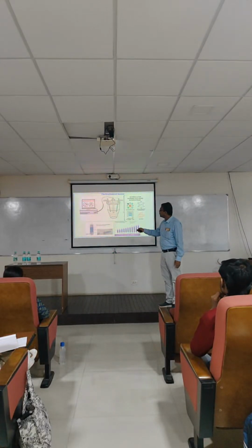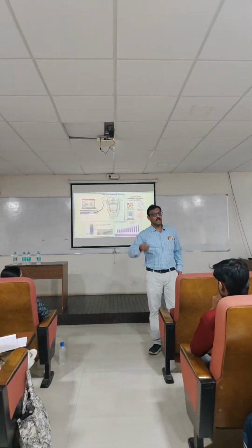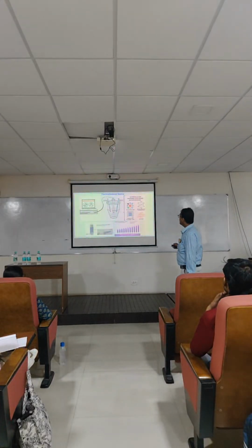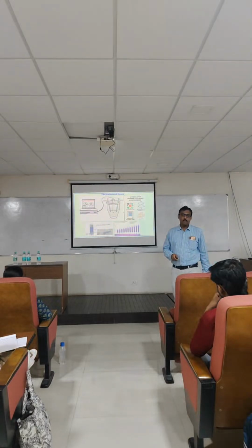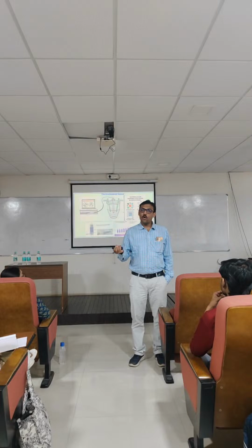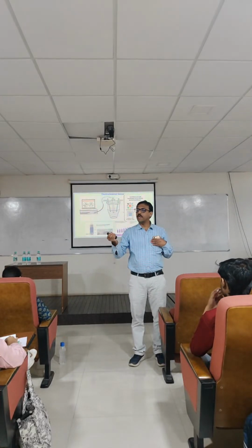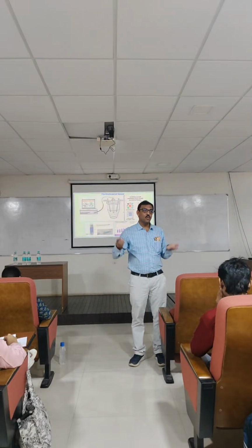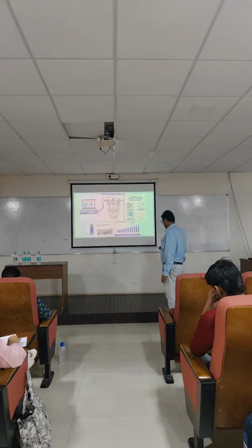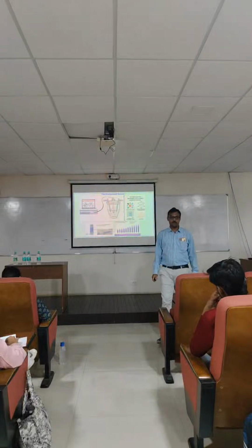Then we measure, this is called cyclic voltammetry, and from cyclic voltammetry, amperometry and other things we are also getting. So these are some signals we are getting from the electrochemical sensor. But this electrochemical sensor, whatever we do in the lab, you cannot always take it into the field. So in the field you will have to take some other system which is equivalent to that three electrode system which is shown here. So that's why nowadays you are getting this kind of strip.